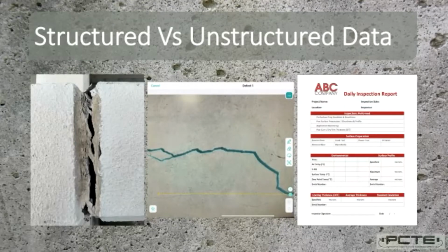So if someone's coming back and wants to see all of the evidence on insufficient cover, they'd capture radar scans, cover meter measurements, physical drilling and inspection, all as one point, because we've taken the chance to categorize it. A couple more kinds of data.